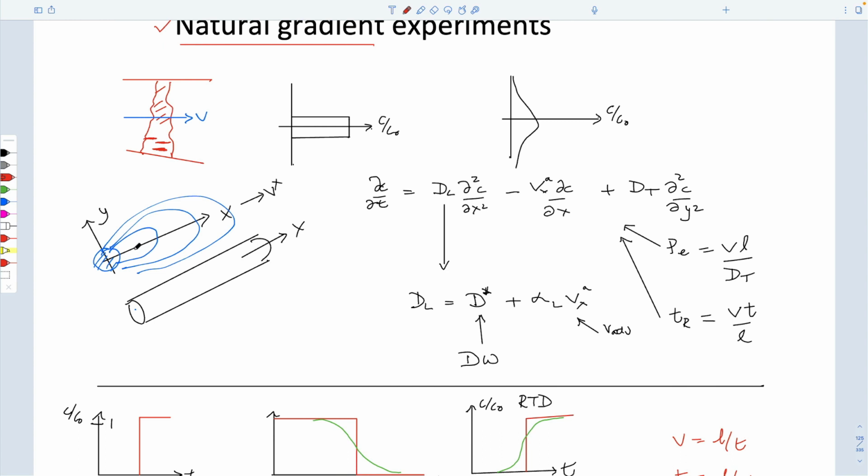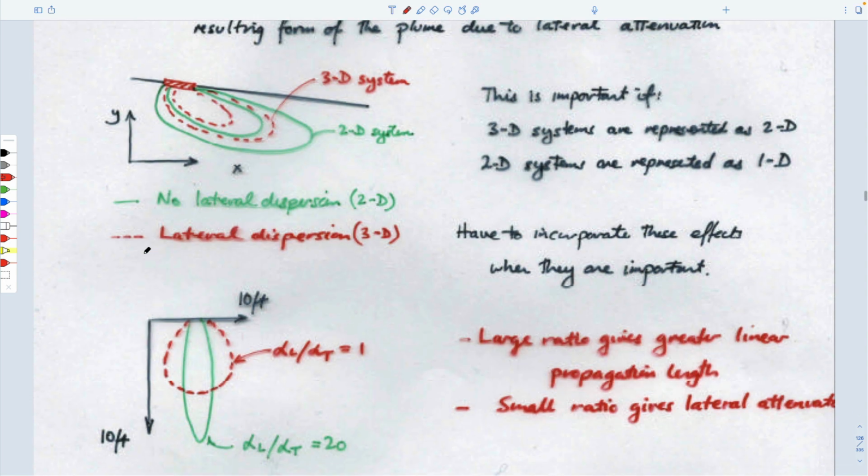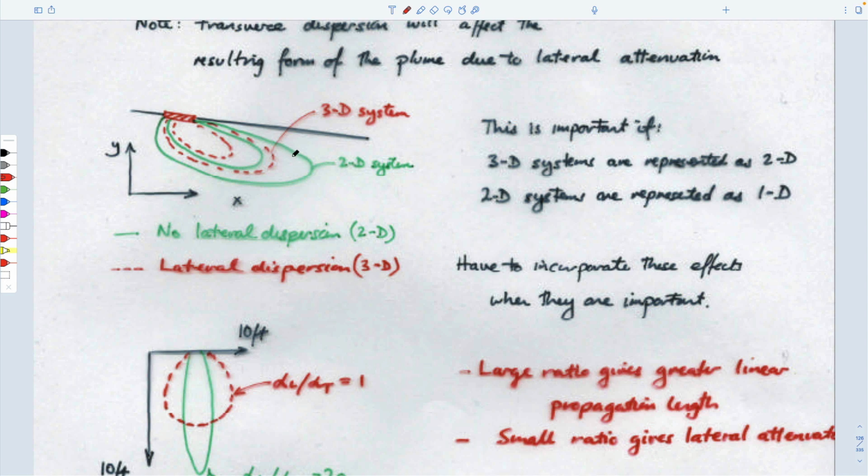And I suppose if you're not constraining it to follow a single path along a tube, if you allow it to disperse laterally, then you could imagine that you're reducing the concentration in the middle because it's dispersing outwards to the sides. And so the concentrations you'd have within this main plume would perhaps be reduced spatially. And so if you took a section across it and you looked at it being constrained in one dimension or two dimensions, and allowed it to spread laterally, then you'd see that maybe the concentrations would get less far downstream because it's also expanding out laterally in plan view.